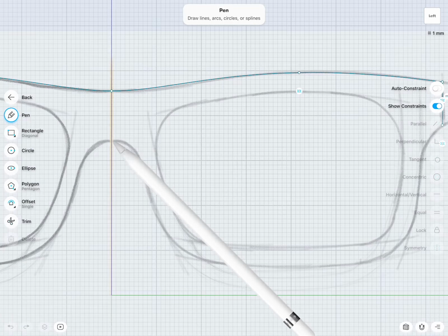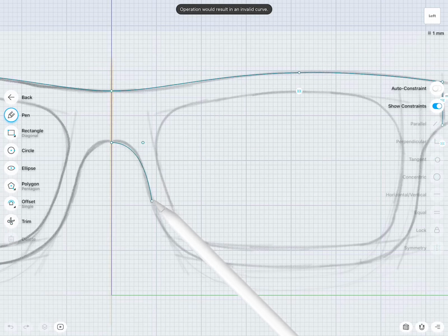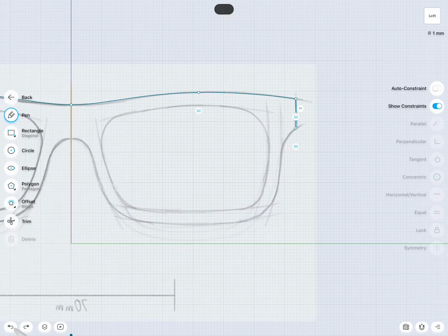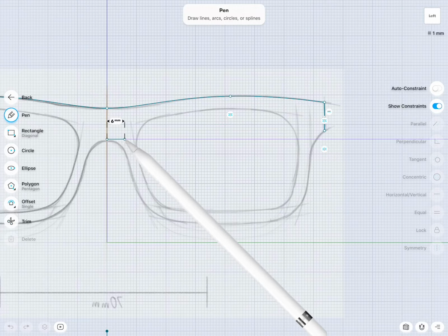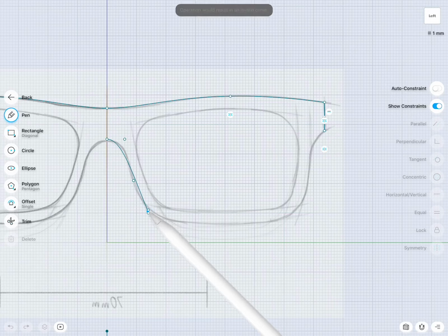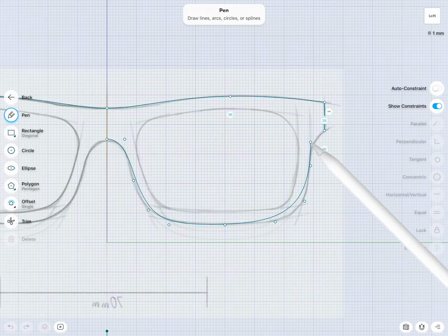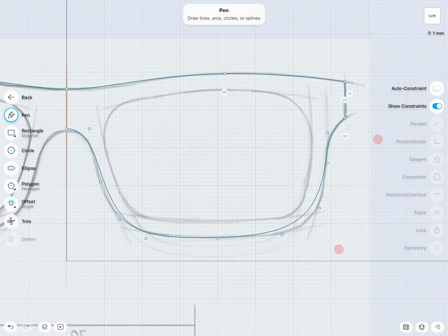I will start again from the left side. Click, click, and the rule kind of is for a corner I need 2 points. And then if I want between two corners arc or bend, I need another point. So click, corner, corner. This bends, click, corner, corner. Oh, I released the mouse button. Let me redo this. So symmetry, arc, side, corner, corner, center, corner, corner, center, and then here's my corner. Very good.